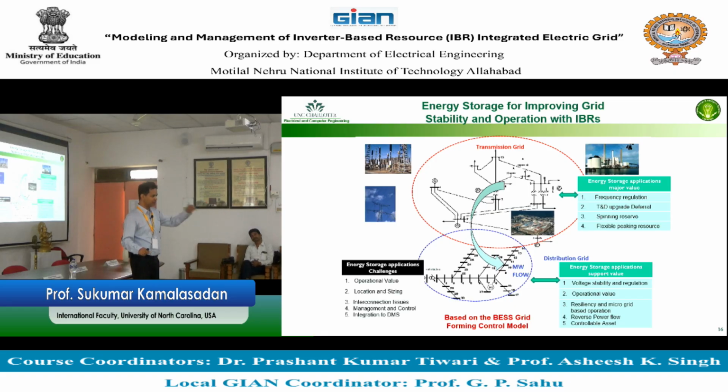So two inverters: one inverter is for the entire PV farm, another inverter for the energy storage, and that energy storage inverter I control. I don't manage any of the PV. I just leave the PV, whatever it can do. So when we were implementing this in the utility, we divide them into controllable assets and uncontrollable assets. Uncontrollable assets are the ones which do whatever they want, like photovoltaics. Controllable assets are considered as battery energy storage. And then you manage the control apps.